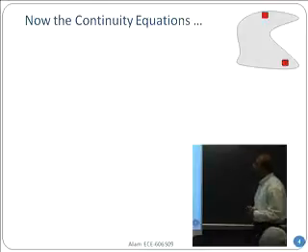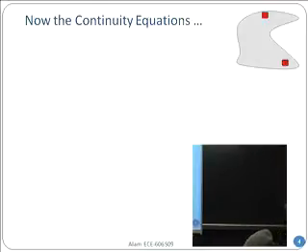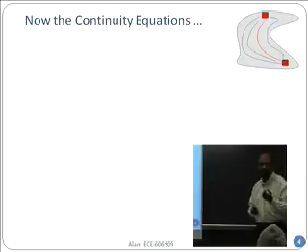So long as electrons are neither created nor destroyed in a global sense, these relationships will hold. Let's consider a semiconductor of arbitrary shape, shown here on the right in a top view. The ash-colored region is the top view of a semiconductor, and I have put 2 square-shaped contacts there. If you apply a voltage, the current will flow from one contact to the other. Now assume that I have divided this region into many minuscule squares, or in 3 dimensions, many minuscule cubes of size A. This size is not, of course, atomic size.